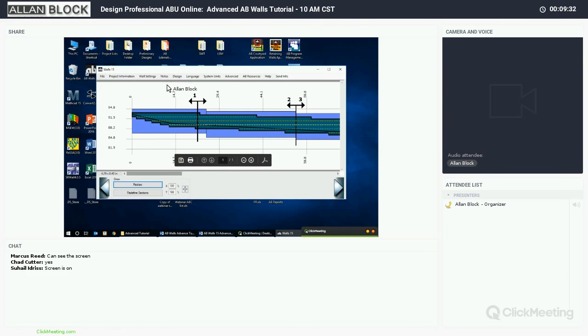I can toggle up, and maybe I've got that 13 course high wall, and being 8 feet, I want to bury a full block here. And so I'm just modifying that. But if I hit calculate, then you can see I've got an 8-foot high wall carried over some of the information that was in section 1 there with a 3-to-1 slope and a little broken back slope. So it's very simple to do a very quick cross section, and it makes it very easy to provide some recommendations or answer a quick question as we go.